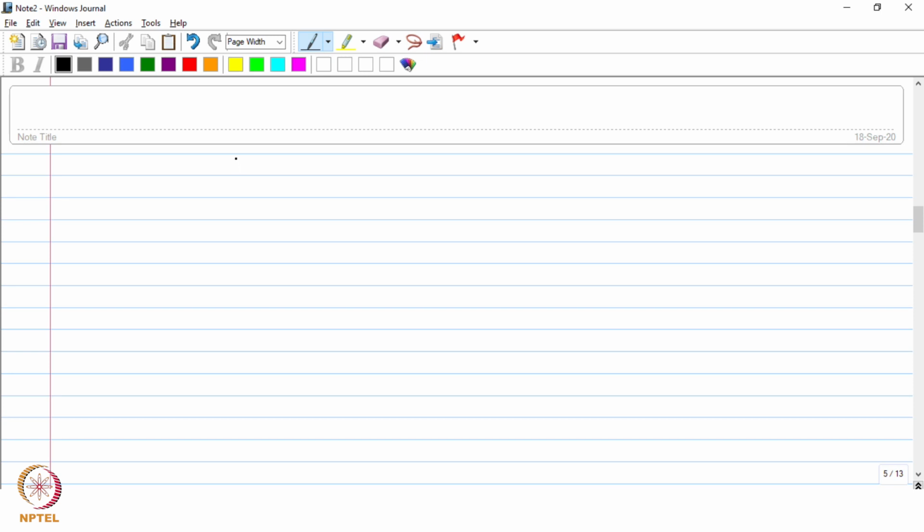Now, as that happens, we will have the restoration occurring, which basically means that you are going to generate strain-free grains from those strained grains which are present in the cold worked material.